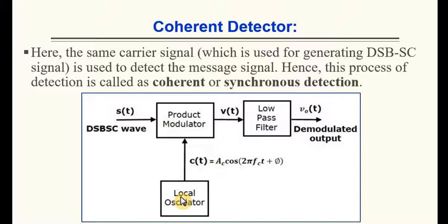Hence the process of detection is called coherent detection or synchronous demodulation. What I mean is that the carrier signal at the receiver should be synchronous with the carrier signal at the transmitter.